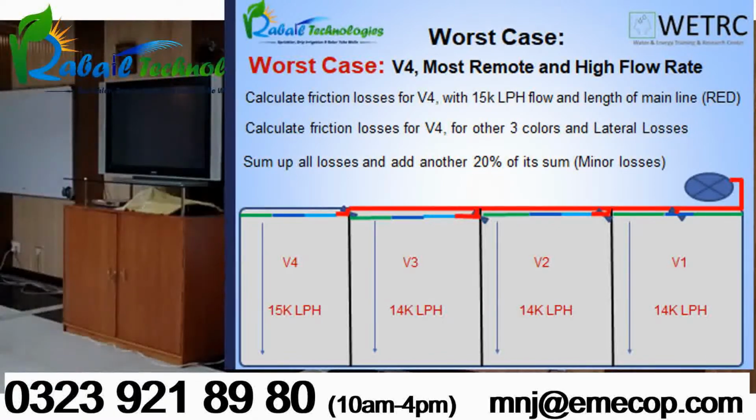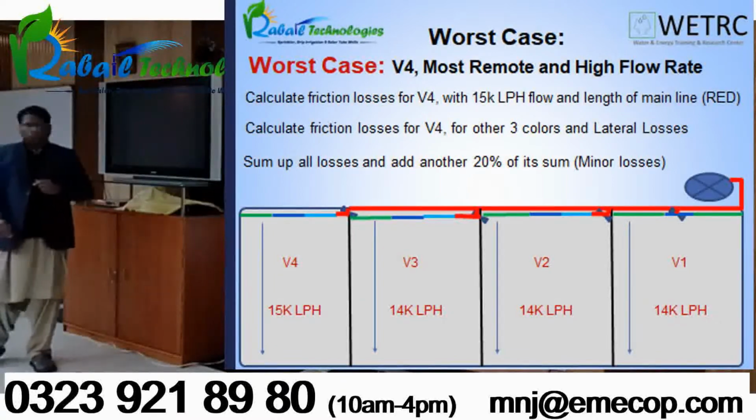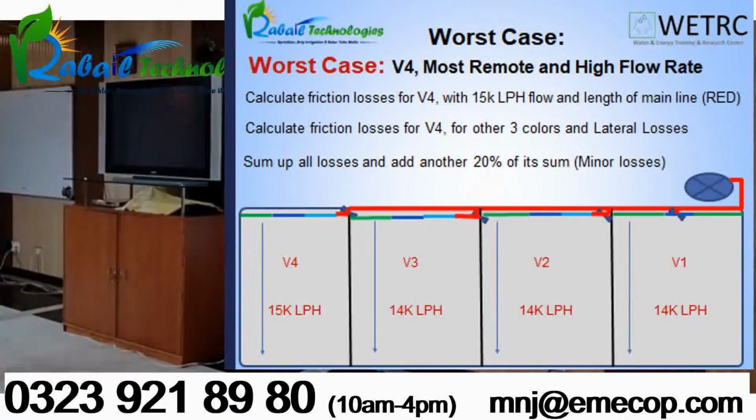Being a beginner, you have to calculate friction losses for a flow of, let's say, 20,000 liter per hour and a length of this much for 3 inch diameter. Then calculate for 10,000 liter per hour with this length, 3 inches. Then you need to see whichever is highest, and you have to pick the value which is highest. Remember, don't sum it up.